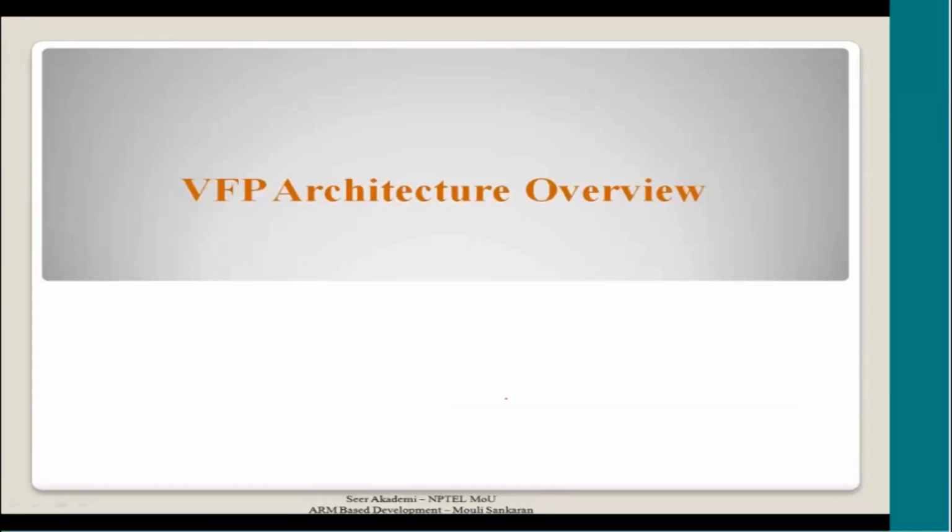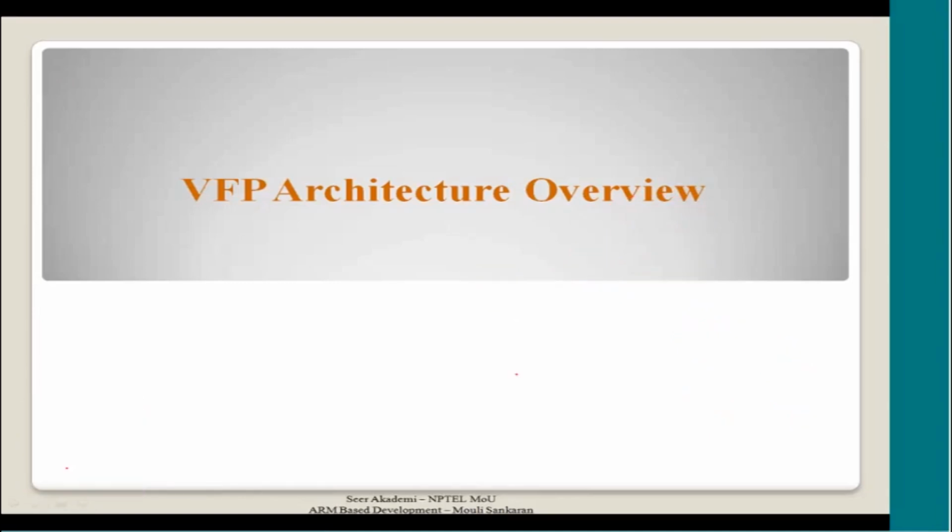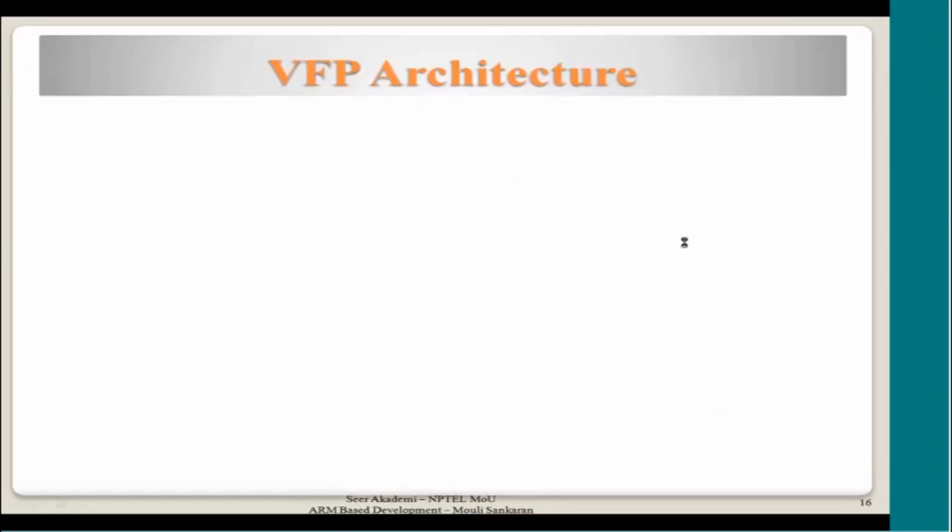Fine. So this is a very quick recap of what a vector processor and a SIMD architecture are. A vector processor in a nutshell falls under SIMD, that is single instruction multiple data architecture. It gets a single instruction, but there are multiple processing elements, and they work on multiple data and produce multiple results. So it is a parallel architecture, because more elements are running in parallel.